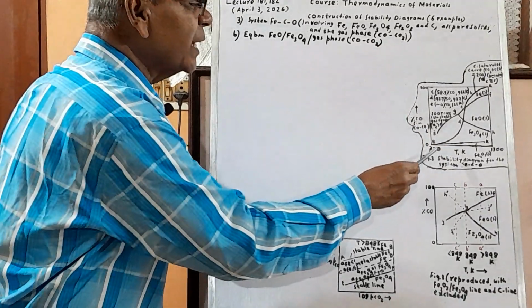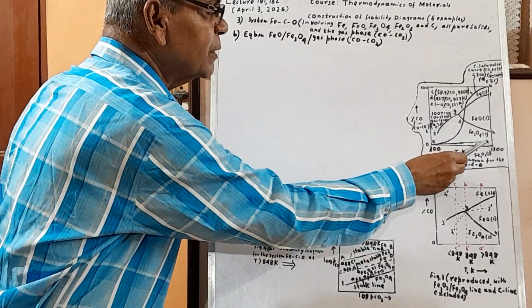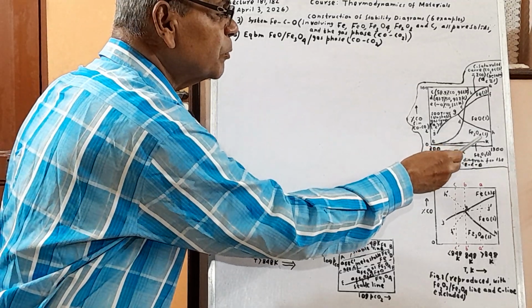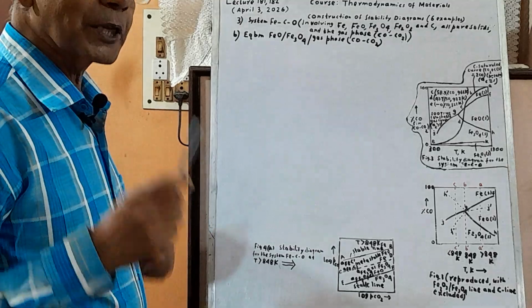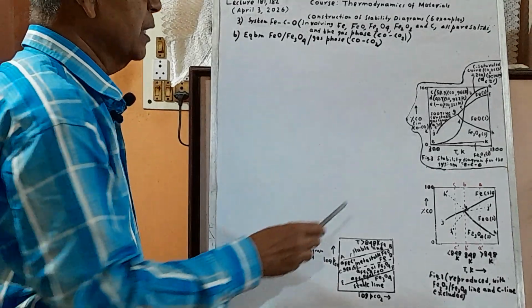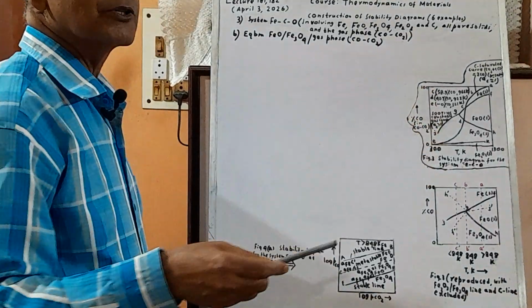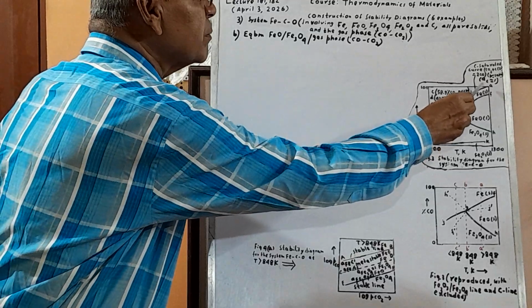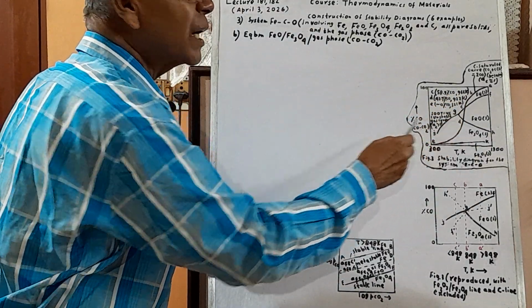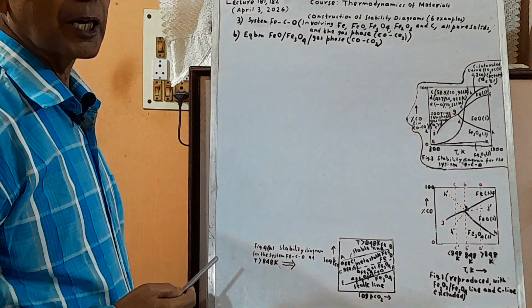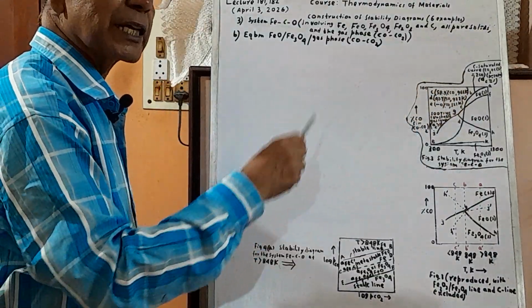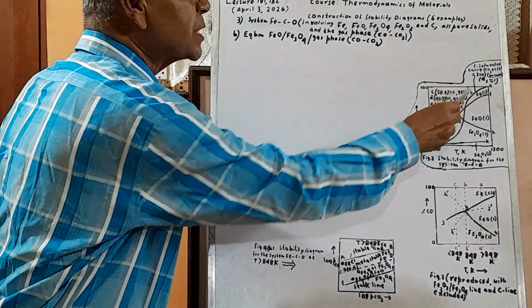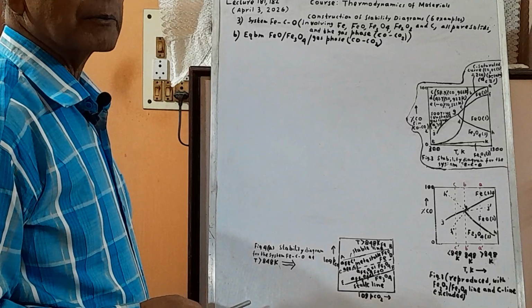And then last we will take up this curve, EK, that is Fe3O4 and Fe2O3. So we will go down to the stage of Fe2O3, and superimposed on it will be this curve, A, B, C, D, E, means the carbon curve, the famous carbon curve, that is the reaction CO2 plus C is 2CO.